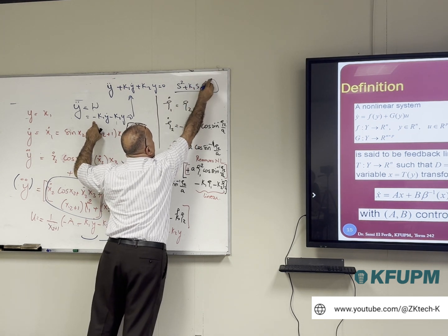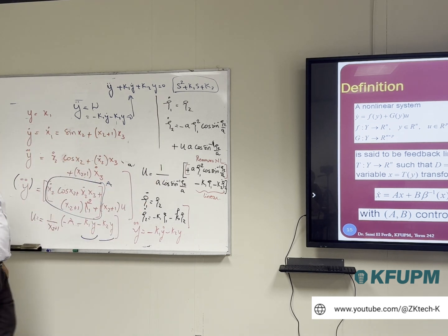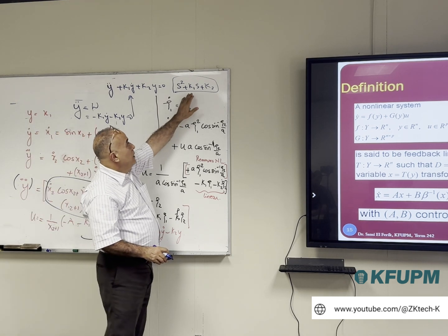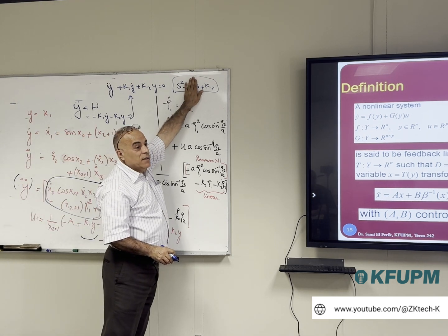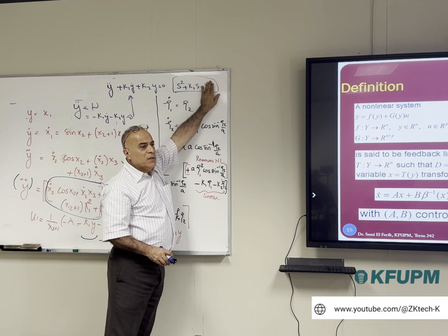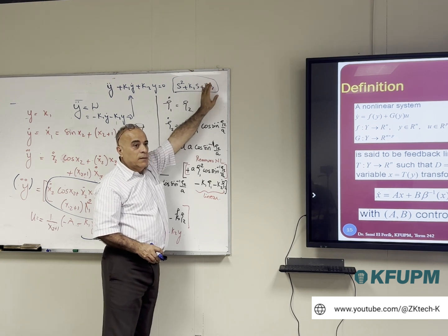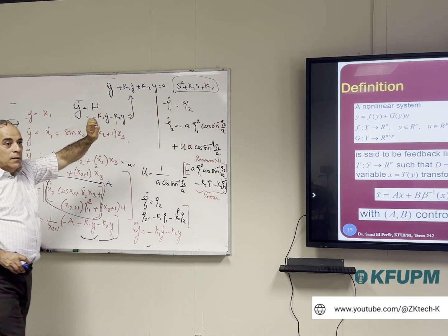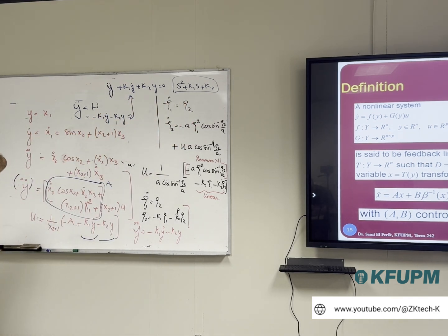So according to Routh, this polynomial has to have all coefficients non-zero and all the same sign to be stable. For the second order it is necessary and sufficient. For higher order it is necessary only, and then we have to make the roots stable. If I remove this term, the system is marginally stable. If I remove this term, the system is going to infinity because we have an integrator at the end. It's not unstable, but it goes to infinity, so it's like unstable.